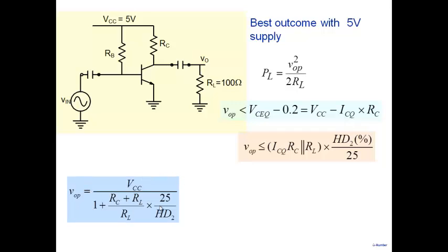All right. So now that you have this expression, you want to know what is the best that your amplifier can do. So even without designing, what is the best V0P that you can have? This factor, (RC plus RL) by RL, can be at the most, if you choose RC very small, 1. You want this factor to be as small as possible in order to make V0P large. So at the most you can have it equal to 1.